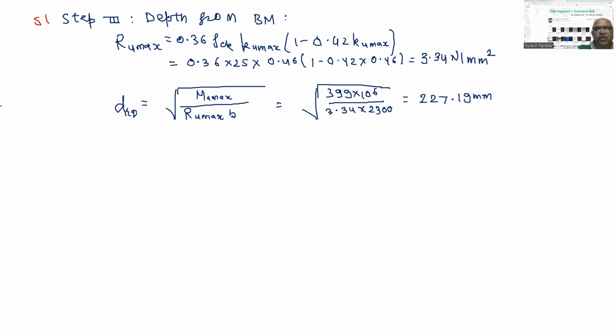And we have to go for 150 actually. We have to add around 200 in it, same as our isolated footing. So always go on higher side. So provide overall depth, and that is equal to 450 millimeters. Because check should be satisfied.